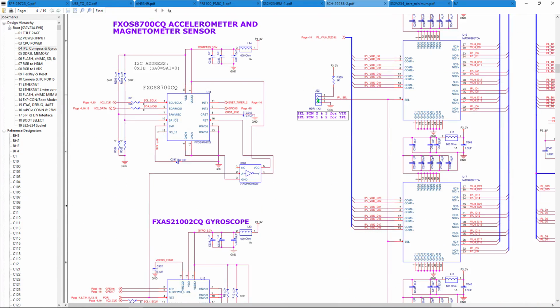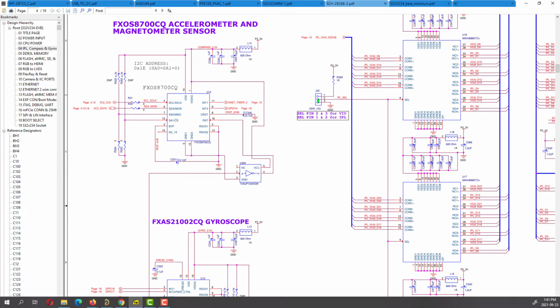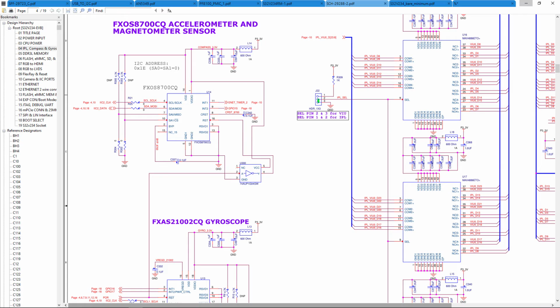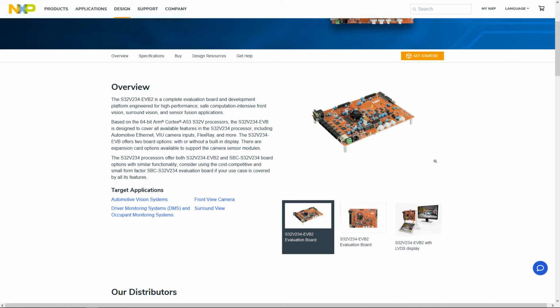All right, so then we move to the third part where you have the compass and the magnetometer. Now, when we design this board, the thing is, every processor, even a microcontroller, would have a couple of pins, and each pin can be multiplexed to have different capabilities.